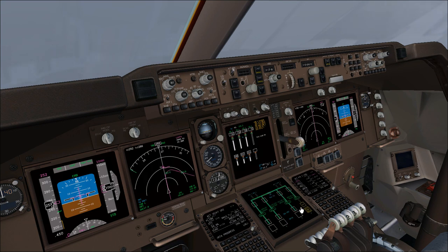Electrical, you can see we have lost generator 4, so bus number 4 is powered by the other 3 generators with the cross connection, and in this case the SSB is closed, so all the generators are cross coupling the loads. They are actually paralleling the load. To make this possible, the generators must have a correct output, and when we have the correct output, the generators control themselves with a load controller that controls which generator must speed up, which must speed down, keeping the loads shared between the 3 generators.